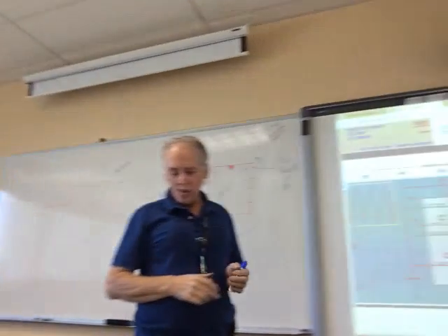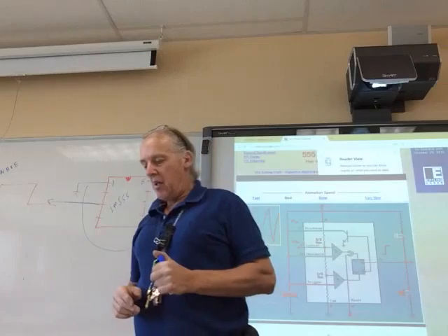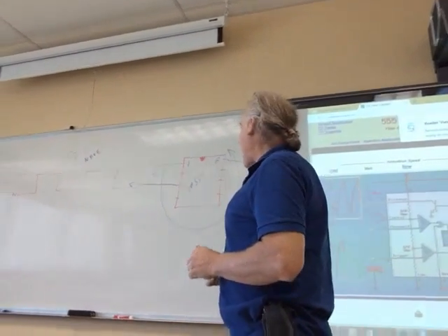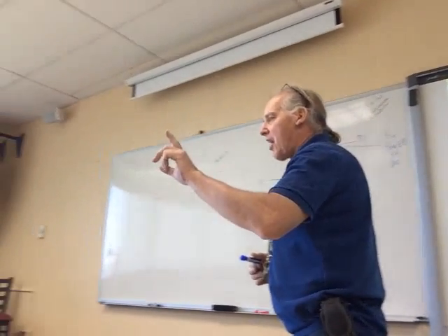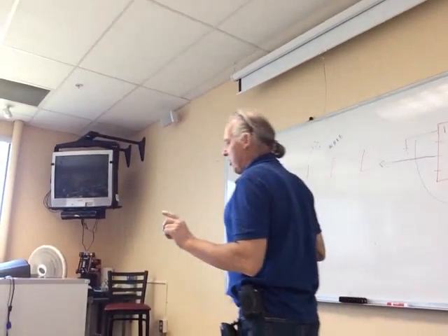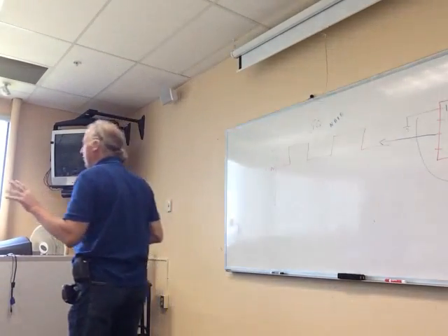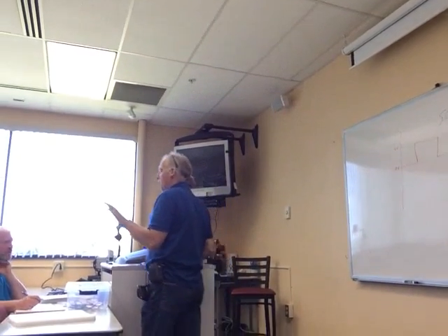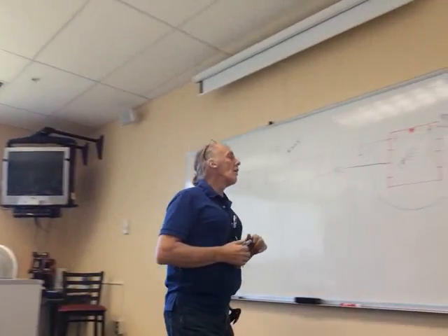And it will produce a square wave of 0 to 5 volts. And remember I talked about inverters and how they would drive 6 other devices? This will too. It acts just like inverters, okay? Drives 6 other devices. All right.